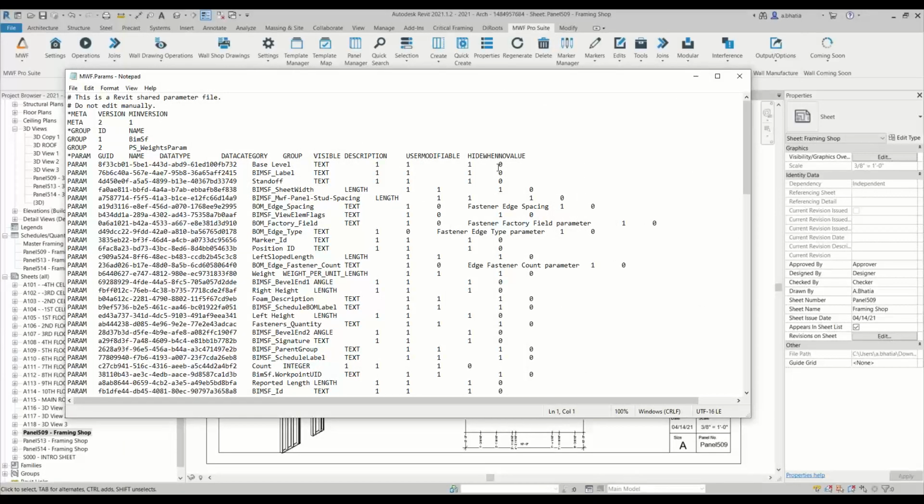So sometimes I connect my shared parameters with MWF shared parameters to create schedules. Is it better to have one full shared parameter file, or to have two separate ones, with the ones I use for the base model and then just leave your parameters as they are in their own file?